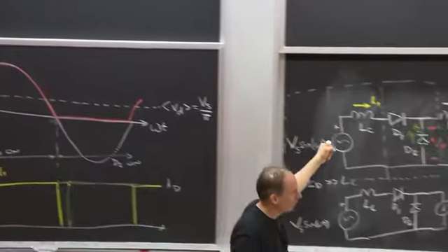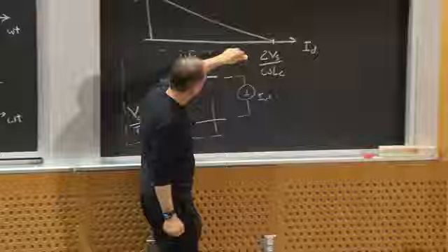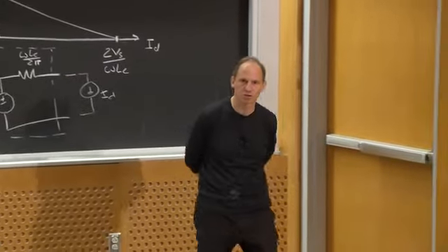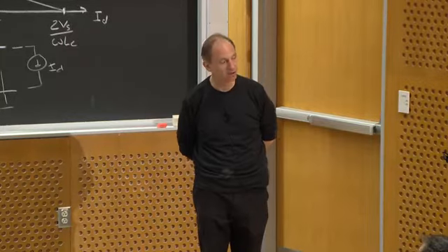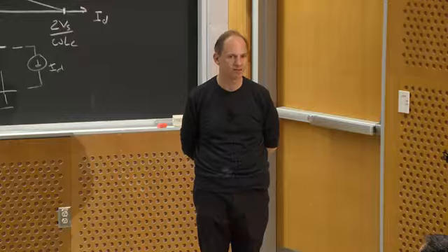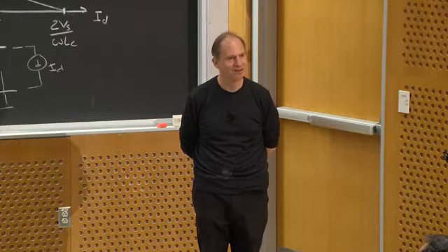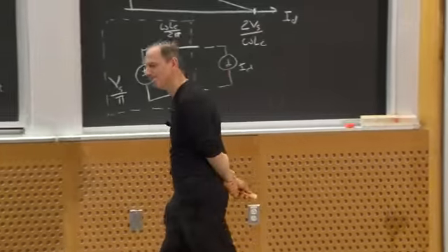Even if your commutating reactance is small, it's what's going to limit, ultimately, how much current it will synthesize. So if you wanted to calculate the short circuit current, that's how you would figure it out. You'd have to include that AC side reactance, even if it was small. So maybe in that sense, it's a good thing if your currents don't go off to infinity. They only go off to, you know, some really big number that you don't like.